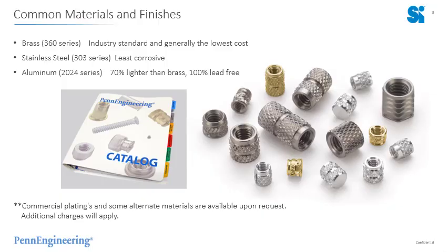We can apply commercial platings to our inserts. It's not very common, but you will see it in situations where you may need a coating due to the mating hardware being used, or some sort of plating used to make it less corrosive, I suppose. Those are available on request, and they will be considered specials.